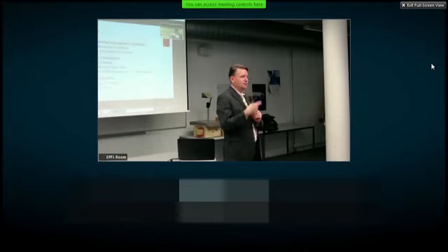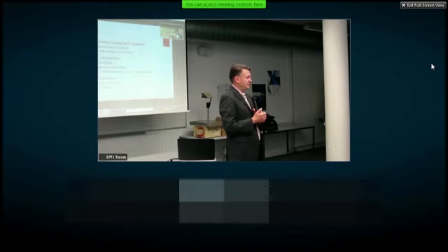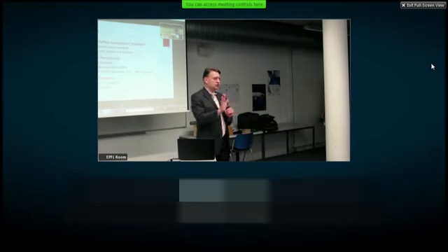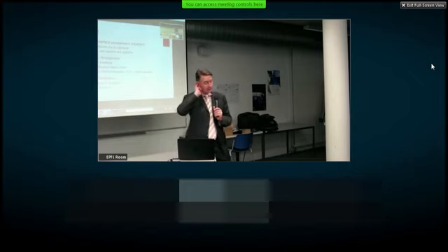My mission got screwed up because of your box. And then it turns out you actually implemented an interface that's in conflict with the ICD. The supplier will step back and say, that's not my problem. You didn't follow the interface definition, and just changing one pin or one polarity can lead to a system failure, right? So you have to pay a lot of attention to the details here.